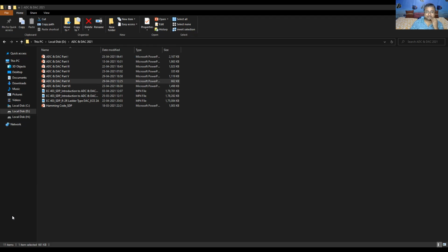When the 2 to the power of nth clock pulse comes, the counter is again cleared. The 1 to 0 transition of the MSB of the counter occurs, and it sets the flip-flop that controls the state of the switch S. Set of the flip-flop means the input is 1, then it will be 0.